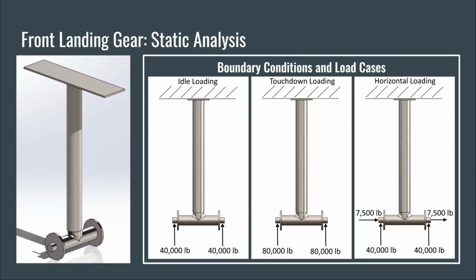A static analysis was conducted on our design for the plane's front landing gear. The free body diagrams on the right show the boundary conditions and the load cases used in this analysis. The boundary condition is the fixed plate at the top of the landing gear where the landing gear is mounted to the rest of the plane. The three load cases are an idle load, where the plane is parked and stationary, a touchdown load, where the plane is making a hard landing, and a horizontal load, where the landing gear encounters a small collision during taxiing.